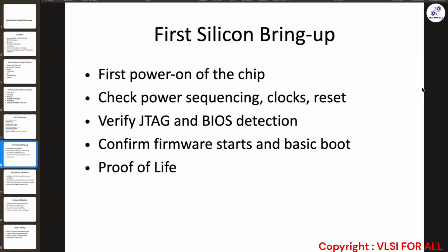It is more like checking whether the silicon which you received is properly working, whether you are able to boot with that silicon, with all of these checks. That's what we do in the bring up phase. In terms of tools, we might use oscilloscopes, protocol analyzers, or logic analyzers, all of that in this phase to debug if you are finding any kind of issues.